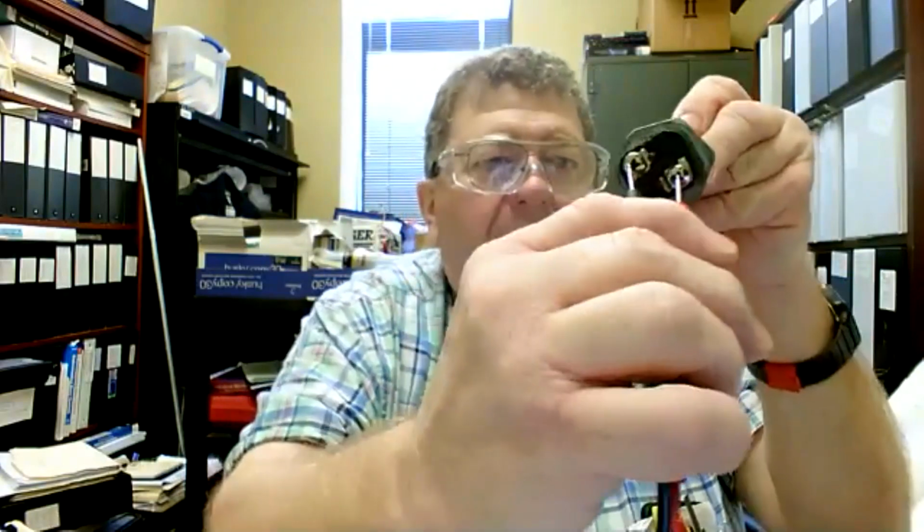You would check your meter on a known live circuit to make sure the meter is functional, and then you would come up here while it's still wired and checking volts. You would check voltage directly across the heater element like that with the wires there, and make sure that it's dead, that the breaker is in fact off. And then you would remove both wires from the heater element, and then switch your meter to ohms.